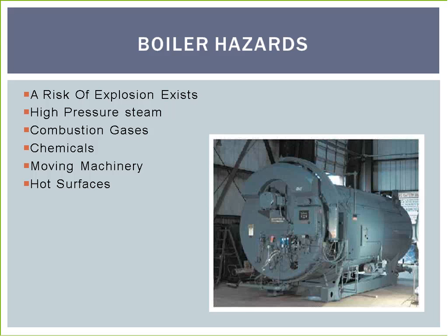There are 4 major categories of catastrophic failure which exist in the boiler itself. The first is meltdown. This is a result of the heating surface metal reaching its melting point. It is a result of the boiler operating on very low water conditions. This by itself will not cause an explosion, but will do major damage to the boiler and create a dangerous situation which could lead to an explosion.